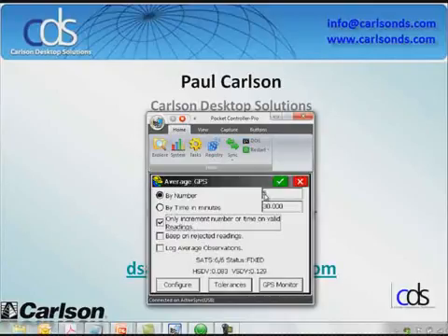If I turn that on, it's only going to advance when it has a good reading. I can tell it to beep on rejected readings. The data collector beeps at me enough because I'm not the brightest bulb in the box sometimes, and I've got fat fingers and I push buttons I shouldn't push, and I get beeped at all the time. And if you've used the SurvCE GPS, you're getting yelled at by the receiver too. So this is your preference, but I think I get beeped at enough, so I don't turn that on.